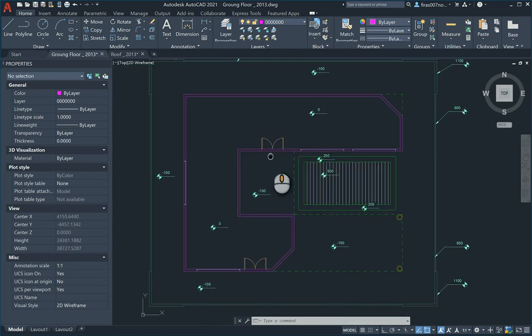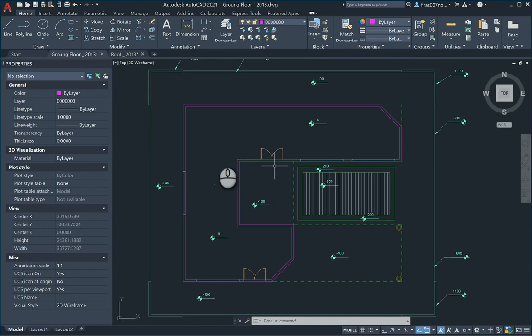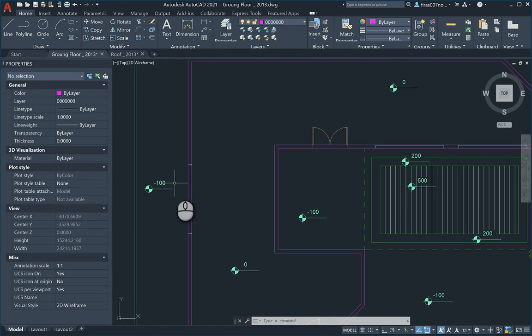And the basic rule that we spoke about several times in the lecture is that for the exterior wall, when you send them to Max, you have to follow their location, or their level, the Z value. Always look at the lower level on both sides. So if it's 0 and here minus 100 and here minus 100, you have to place them at minus 100 in 3D Studio Max.